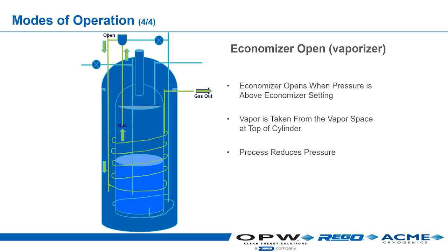Here's my other example. Got a welder, he closes up on Friday, turns everything off, comes back to work on Monday. As this liquid cylinder sits, heat's getting in there. It's been sitting for 2 days, right? It's going to build up pressure in that headspace. He then goes to use it. What the economizer feature does is it pulls from the higher pressure here first. And then once all that high gaseous pressure has been used for his functionality, depending on where it's set, the pressure builder kicks on.